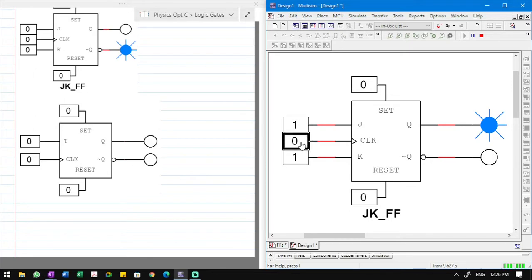So I'm going to turn the clock on, and those outputs should toggle, meaning Q will turn off. So I basically put the circuit into a reset state, but at the same time, not Q will turn on. So that is what should happen when the clock turns on, and it does happen. So I'm going to turn off the clock now, meaning the clock is going to go from high to low. Nothing should happen. But when I go from low to high again, it should toggle, right? So you cannot use the input side of this circuit to put this into an undesirable state. You cannot put this circuit into race conditions.